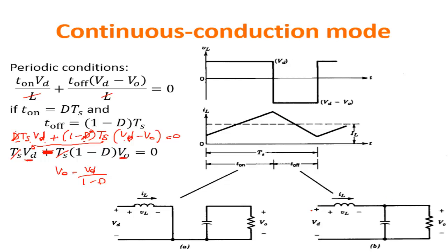So this is ensured by construction. You have an output voltage that can in practice also be very high. If D is close to 1, you can have a very high output voltage. In practice not extremely high, but a few times the input voltage is possible.